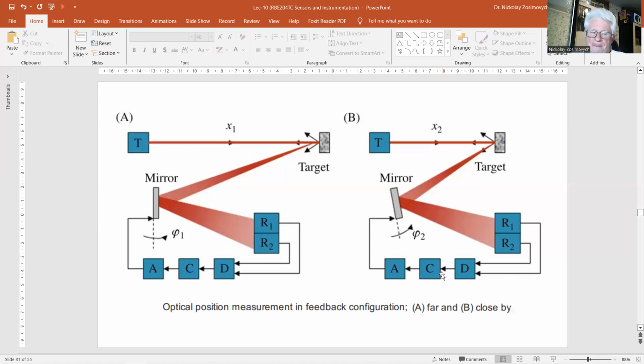uncertainty aspect. For two-dimensional displacement, the moving mirror has 2 degrees of freedom, and the detector comprises 4 receivers arranged in a square. The principle is applied in, for instance, automatic focusing systems in certain camera types. Another application is found in contact-free measurement of profile. Commercial instruments for that purpose are available with a resolution down to 50 nanometers and a range of about 1 meter.